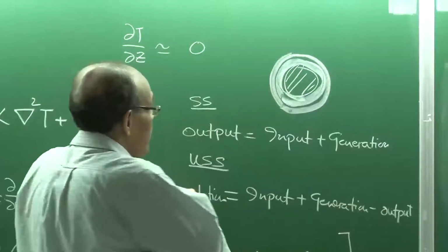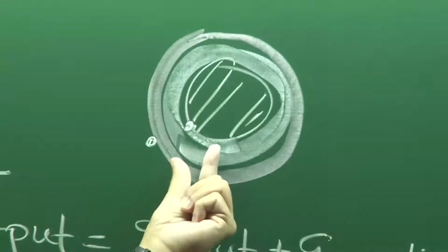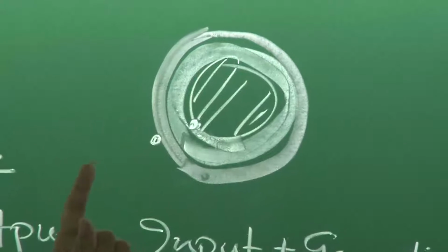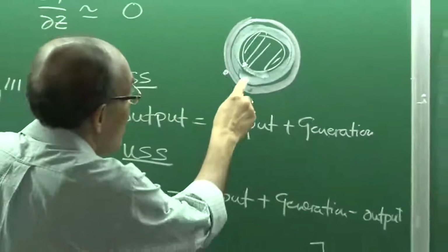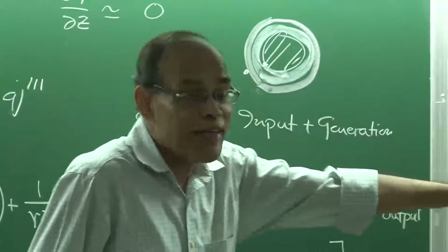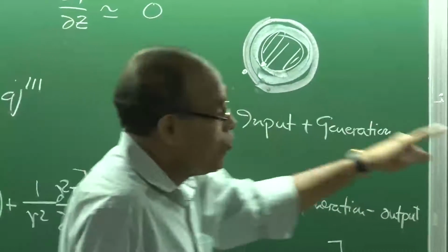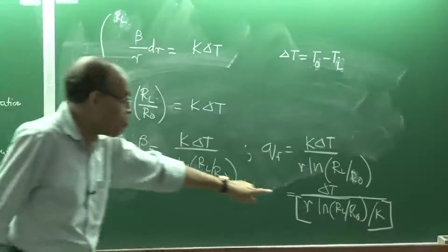So, I can take the delta T between these two surfaces, and then I should be able to find out, if I assume the contact resistances for the time being, what is the thermal resistance of this in terms of this, because this will be my R1, R2, this will be R2, R3. Then I should be able to find out the contact thermal resistance with respect to flux, and then with respect to net rate of heat flow, the R term will vanish.